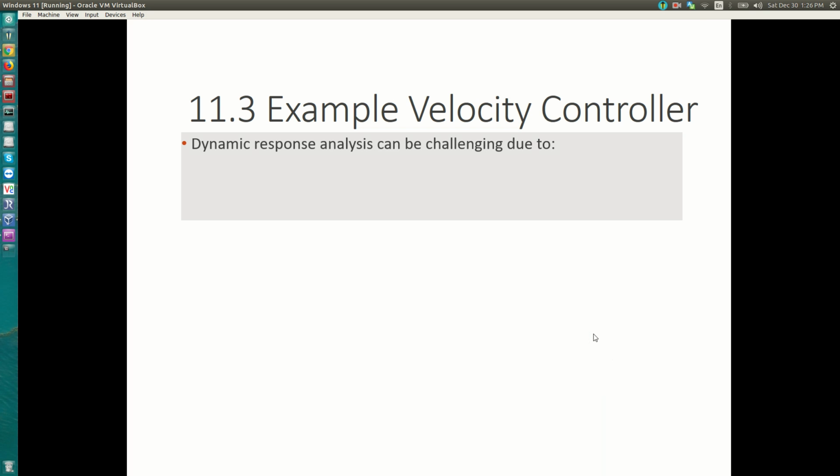But we do face some challenges, as you'll see. One is that the dynamic response is challenging because the second link can drift from the center and sometimes hit joint limits. When there are collisions due to joint limits, we introduce distortions into our system.